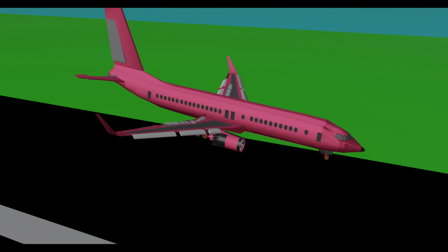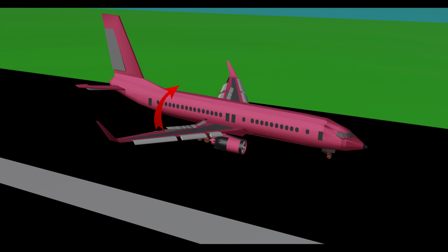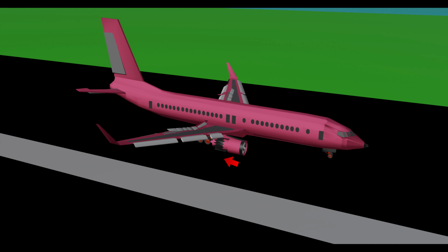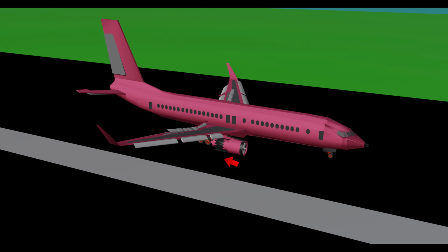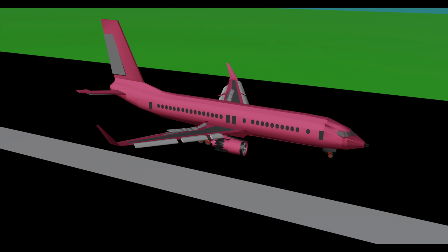Upon reaching the ground, the spoilers are activated, turned and pivoted up in order to interrupt the flow of air and cause drag. Reverse thrust of the engines is also activated, opening the engines up and causing the exhaust to move forward. This therefore increases drag. Spoilers and thrust reversers are used together to aid wheel brakes, which are used to stop the aircraft on landing.